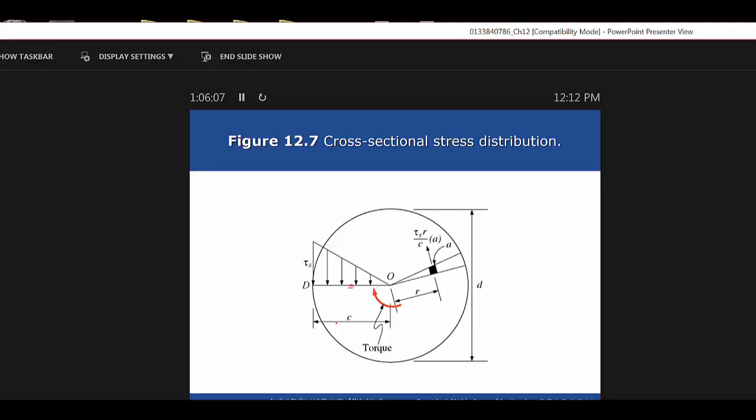So we punched those numbers in, and we should find out that max shear stress is 7,570 pounds per square inch. So that would be a number we'd have to go back and make sure that we were below what that would be for that material.